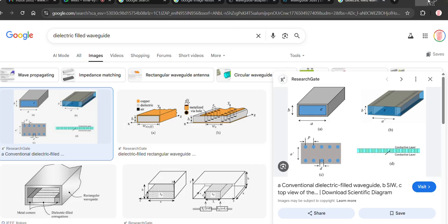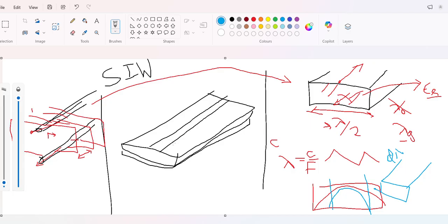But this came up with the idea: what if we create that in a PCB itself? From this original idea, we can think of small microstrip lines and take a via and connect it to the bottom and make this length lambda by 4, and keep on connecting them. The distance in between each of these extra lines is lambda by 10. That way it will be a seamless array of this kind of structures with short circuit at lambda by 4 division.